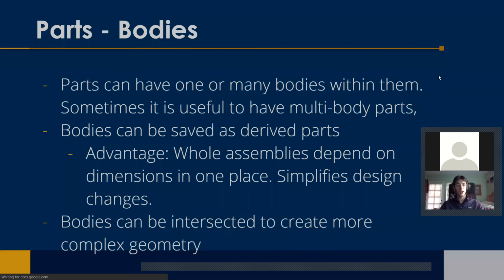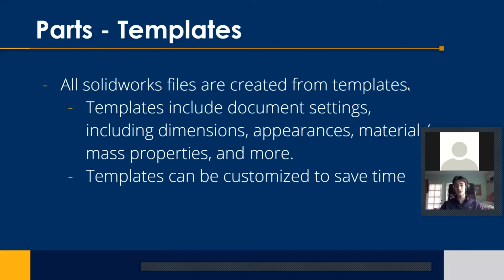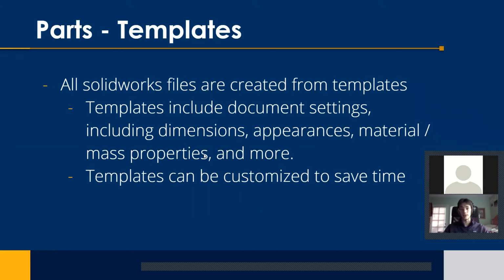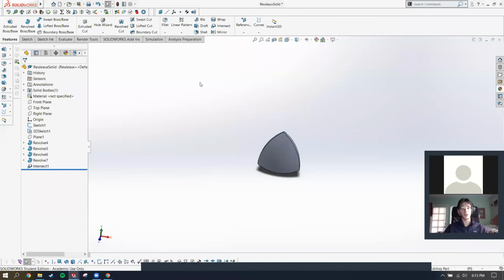Okay. Next thing I'm going to talk about is templates. This is something that's really going to be helpful if you're working with a team. So for example, you're working on a project with many people using SolidWorks at a time. You want to have everyone on the same page as far as their document settings. That just makes it a lot easier to combine and do an assembly and work on it if you're switching between people. The way you do that is when you make a new part,